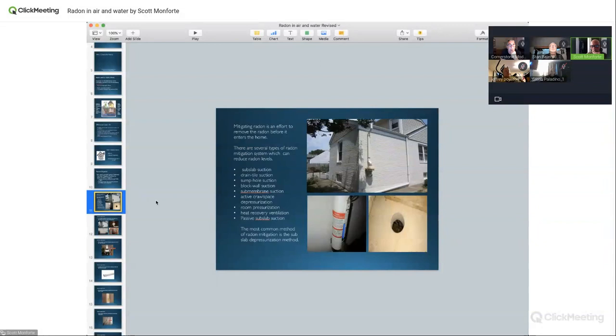That's the important thing. There's sump hole suction. That is my last resort. I've done a few of them. It works. I mean, heck, you've got drains that go all the way around. There are pros and cons to it. The pro of doing it in a sump pit is you have drains that go all the way around, so in a sense, you're sucking all the way around the perimeter of the basement. You get a good draw.